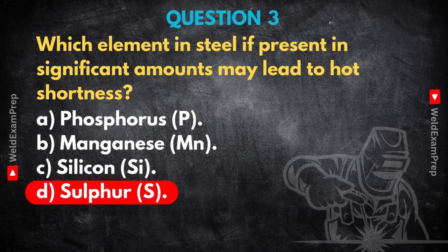These liquid films basically break the connections between the grains. They can't hold any load. And under the stresses of heating and cooling during welding, the grains just pull apart along these melted boundaries. Bang, you get cracking. Hot shortness cracking. That's fascinating. Liquid films inside seemingly solid steel causing cracks. You hear about manganese being added to counter this.